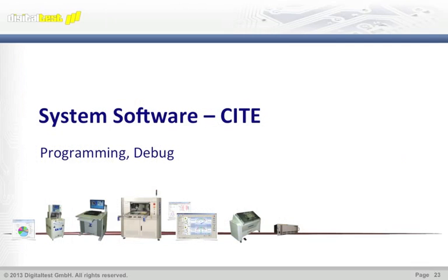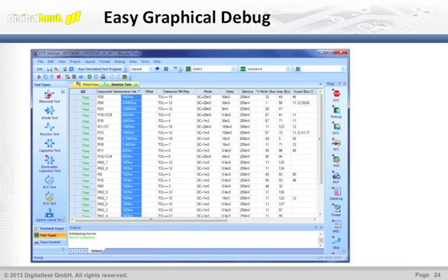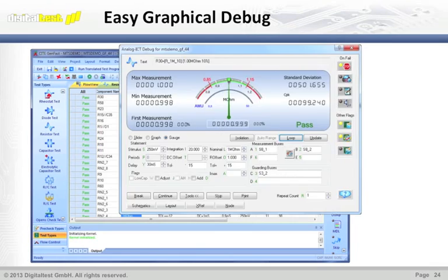Once that's done, we then go into our Site software, and just as a quick view of the Site software, we have facilities inside there such as GenFast that allow you to see all of the data that you want to see very quickly. So you can look, we've got a resistor, this is the value, these are the points we're probing, this is the head we're using to probe it if it's a flying prober, these are the measurements, it passed, it failed. So in debug, it can be very quick and powerful, and all of this is generated through our automatic program generation tools.